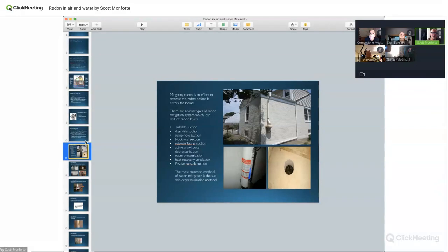Now, there are times it's a very small crawl space. Some of you guys that do inspections, it's under a bathroom or kitchen. It might only be 5 by 5 and it's all dirt. Sometimes I'll just cover that with plastic and not put a draw point in there, and then do the basement and see what happens. Most of the time it's fine as long as it's covered.